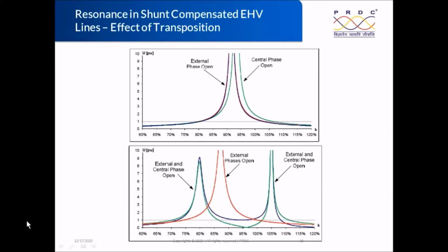Because the right of way is the big problem. But the problem is the trefoil will increase the capacitance when you compare with the uniform placement. The same way here also, tower design, if you go for the compact design, definitely it is going to increase your capacitance values. Because we have seen, right, this coupling effect is due to capacitance coupling as well as inductance coupling, but inductance coupling will be very minimal, majorly dominated by this capacitance coupling. The next, circuit asymmetries, whatever we have seen now, this will again be a high value, because the untransposed lines will have different characteristics compared to the fully transposed.